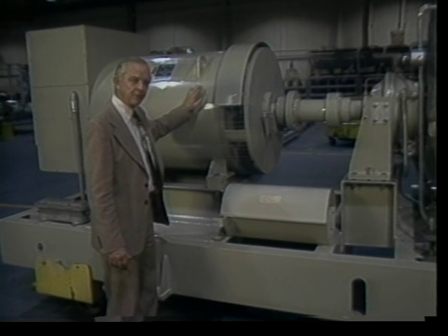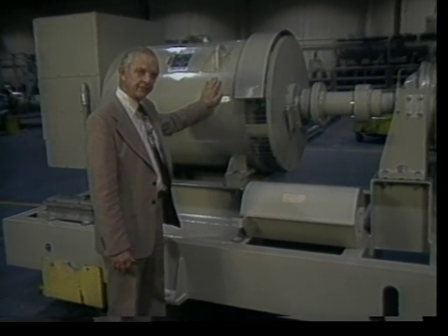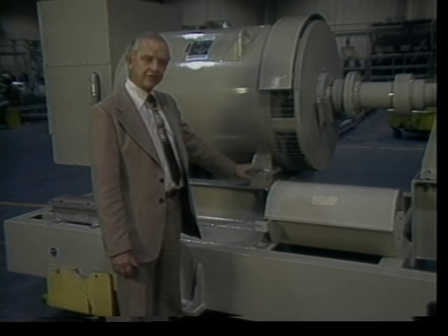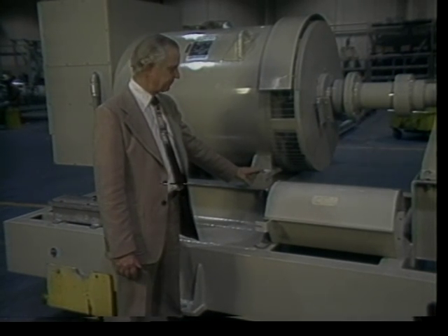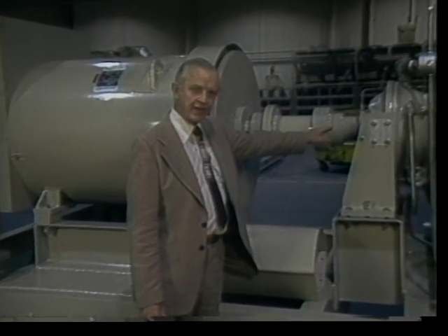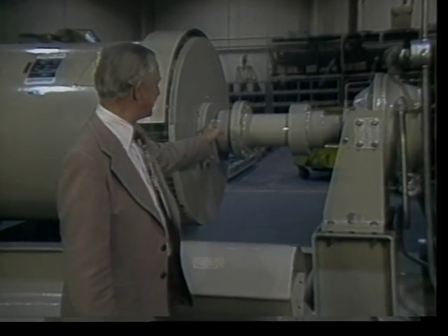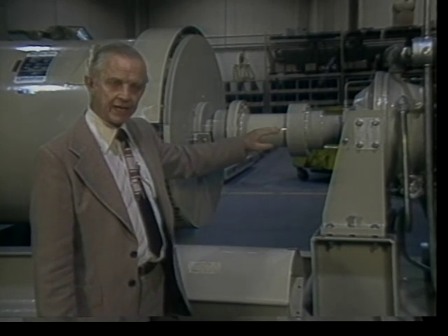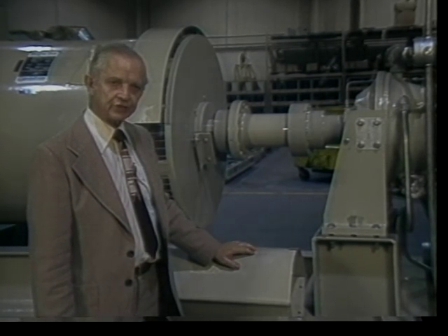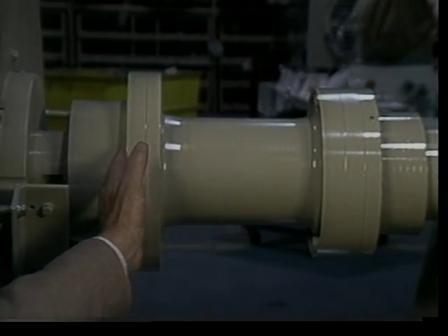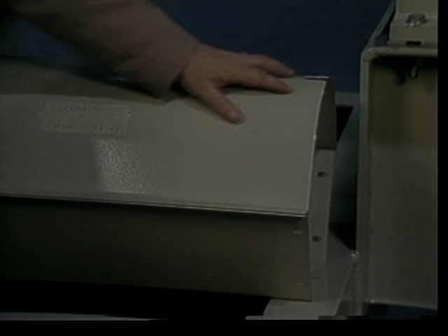The next major component is the driven equipment. This is the AC generator, and it's mounted at the rear end of the skid on the base frame. The output shaft of the reduction drive assembly and the input shaft of the generator are very carefully aligned for squareness and concentricity. The shafts are connected by a two-piece shear coupling enclosed in this protective cover.